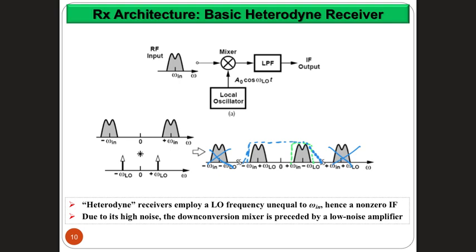Of course, the next stage might be bringing it to zero frequency, which can now be done since we have done our channel selection and removed adjacent interferers. So now we can bring it down to zero, or the baseband, the original frequency of the signal, without much consideration about nonlinearities.